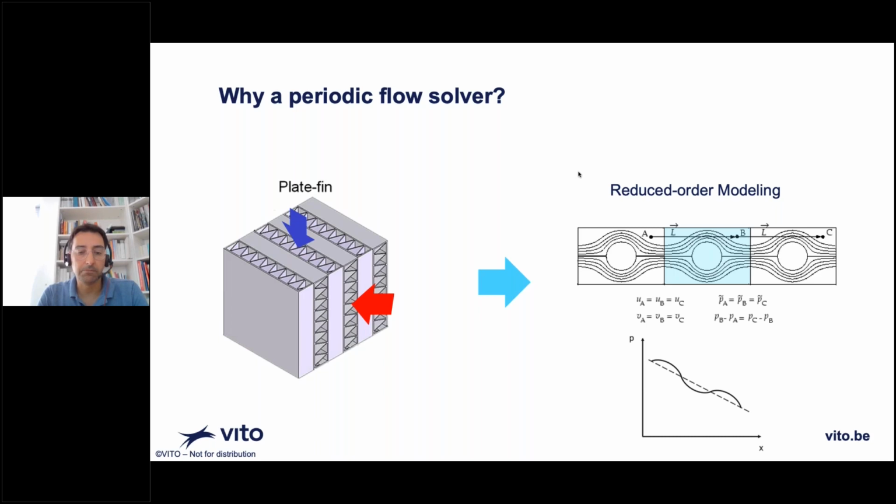Of course, we lose some information when we reduce the computational domain so much. It's mainly in relation to the so-called entrance effects, so the effects that derive from the flow at the beginning of the channel. But apart from these, since the entrance effects are generally limited to a small portion of the channel, the approximation can be accepted, and the reduction in computational cost is large.